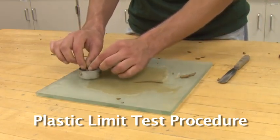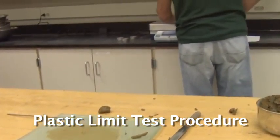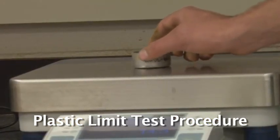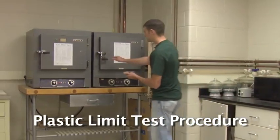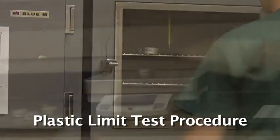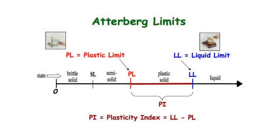for moisture content determination. Repeat the test enough times so that enough soil has been obtained for 2 moisture content samples of approximately 6 grams each. Record the wet weights of the moisture content samples and place in the oven. Reweigh the samples again in 24 hours. The average of the 2 moisture contents is the plastic limit.